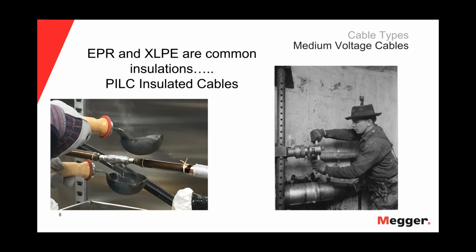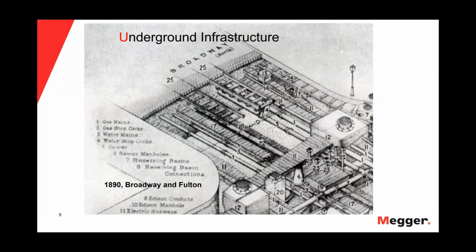And the reason I highlight that with these 2 pictures is these cables have been around for a long time. They're still out there, and they do require some different techniques and troubleshooting applications versus the solid dielectric extruded cables.